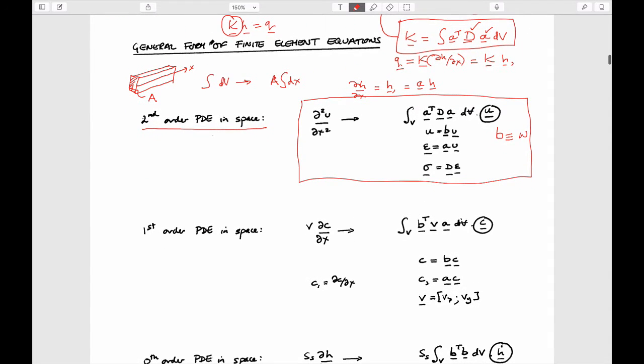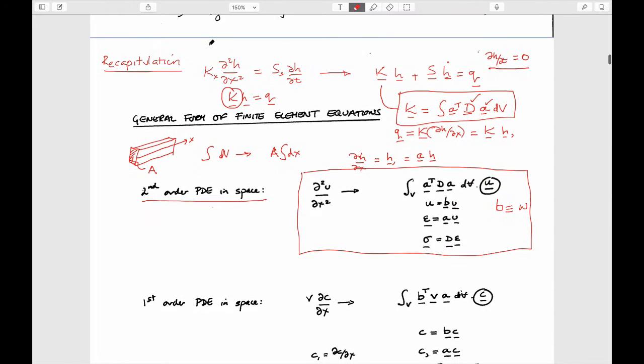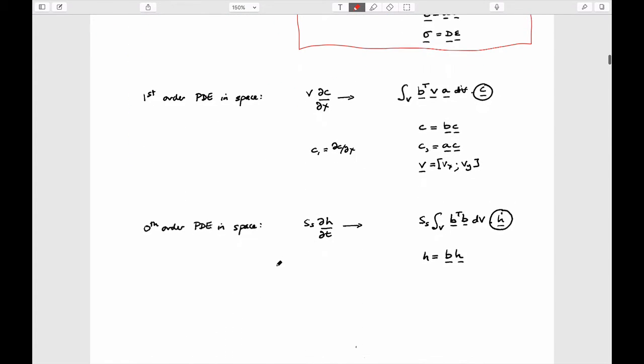We made the point last time that if we were solving the other parts of this equation, we'd want to know what a zeroth order representation would look like. It's first order in time, but zeroth order in space, right? It's constant in space. So the expression that represents that would look like this, and like this. These are just the products of the shape functions of the elements, and we know what those are. So if we wanted to, we could immediately define that behavior.